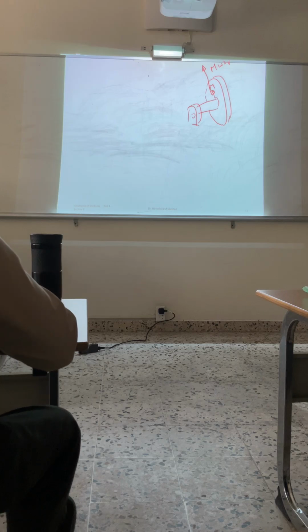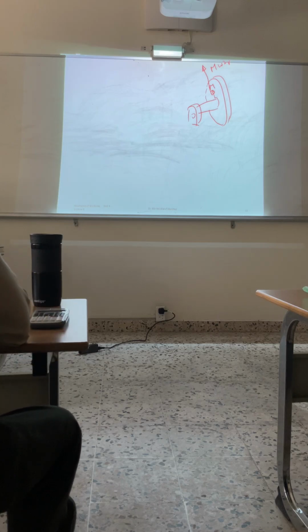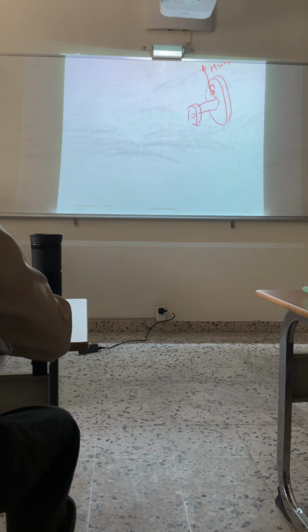Like what, guys? I gave you two examples last time where you are not able to make the static balance. Give me the name of the 2 machines where you are unable to make the static balance. At least one example. Dynamic or static? Dynamic. You cannot make static, and you must add two extra planes to add up the balancing masses. I'll give a name for this machine. Very well known machine. Turbine. Exactly, the steam turbine.